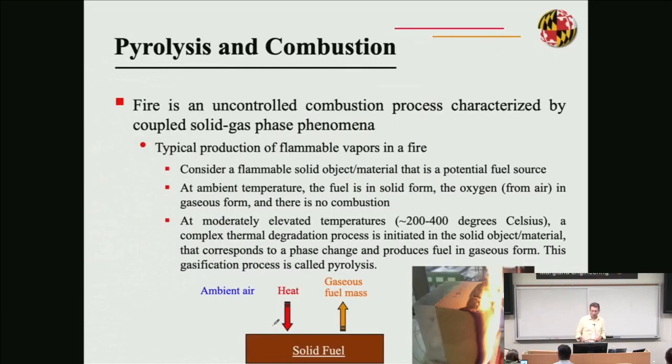So let's talk a little more about the coupling between pyrolysis and combustion. Again, pyrolysis is the production of the fuel. Combustion is the production of the heat. And Dr. Soliarov already described this. You have heat exchange of information from the gas to the solid. The gas is where combustion takes place, and some of that heat released by combustion goes back to the solid, and the solid in return provides the fuel that the combustion process needs to be sustained.